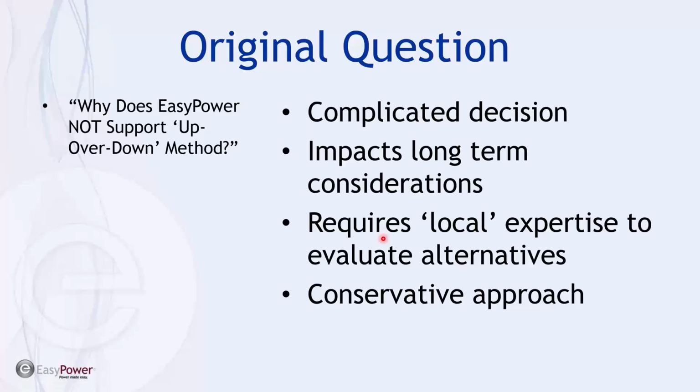The fact is, it's a complicated decision, and even the National Electrical Code requires a qualified engineer to make the assessment of both the series rated combination and the ability to calculate what the maximum downstream current is in the case of the use of the current limiting fuse.